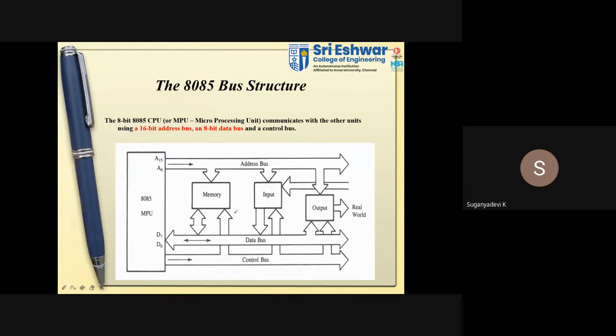Okay, so here is your 8085 microprocessor, which is connected with the buses. Already we know we have A0 to A15, so a 16-bit address bus, and we have 8-bit data lines. Address lines will be 16-bit and data lines will be 0 to 7, that is 8-bit. Here we have a bidirectional one which carries data, and here we have a unidirectional one which carries addresses.